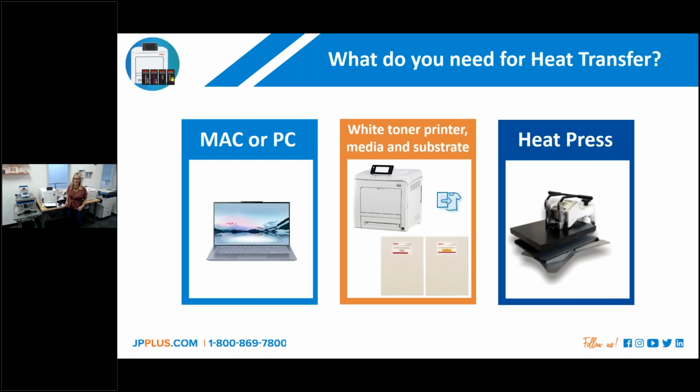Hey, quick question, Carly. It's on the clamshell presses again: other than price, what advantages do the clamshell presses have over another style? Some of the clamshell presses have an auto open, which I find to be very convenient. One of the disadvantages that I really don't like about a clamshell is that it does pop straight back up. If you're doing heat transfer or sublimation, when you're pulling that transfer off, you're exposed right underneath that heat platen. You just really need to be careful to make sure you don't burn yourself and that you have enough space there.